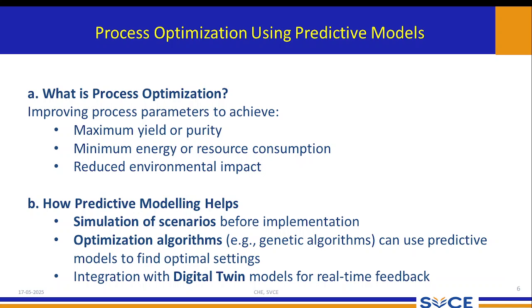The spray dryer needs to give you a product yield. Because of the stickiness nature of the product, the yield may be reduced. So by adjusting the glass transition temperature, we could get a larger amount of yield. Okay, so this is how my process is, maximizing the yield higher.